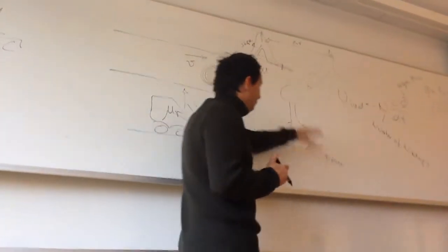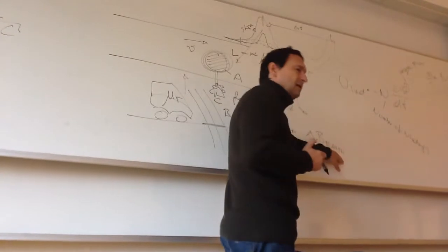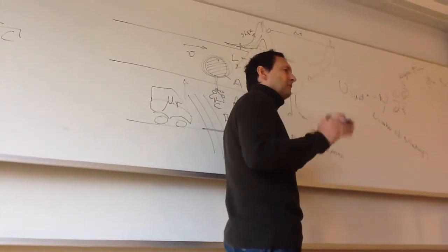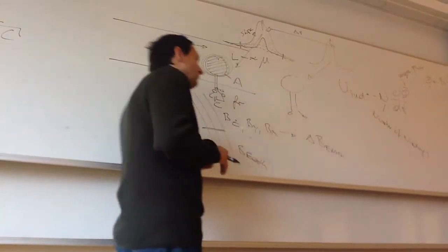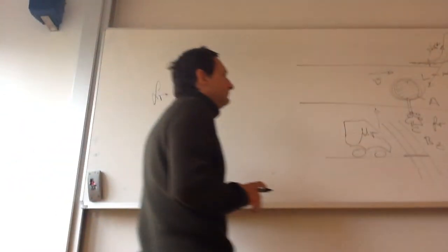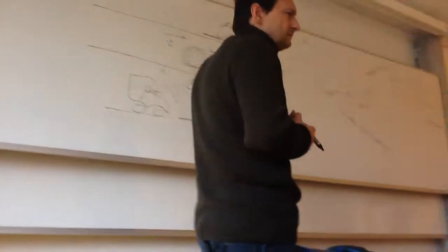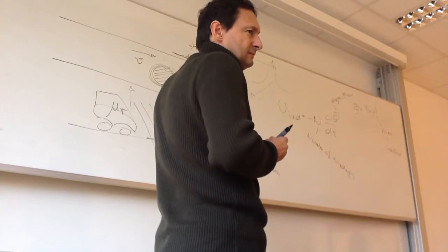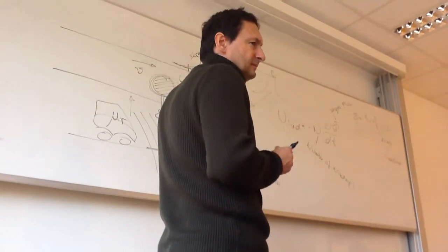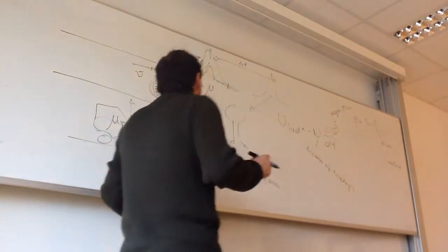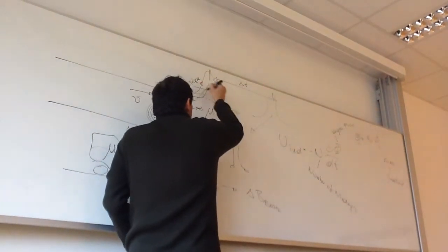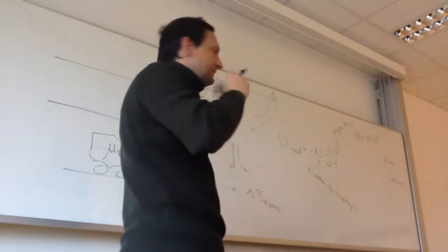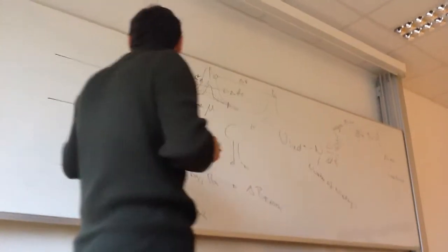But with the induction loop, you are not directly measuring the field components of the Earth. You are only measuring the shift in resonant frequency. That's what you're doing here. One question. Wouldn't you also get a negative voltage when the vehicle leaves the area of the loop? This voltage is proportional to the shift in resonant frequency. Yeah? Oh, okay. There is no change in output voltage here.